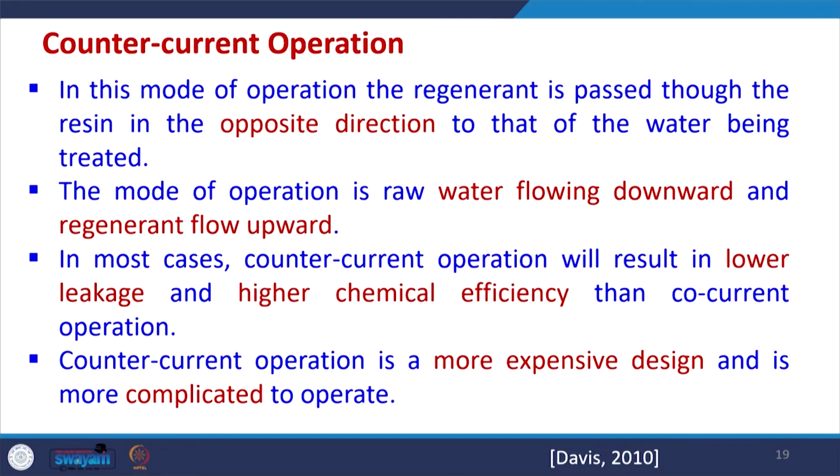Similarly, we may have a counter current mode of operation also. In this mode of operation the regenerant is passed through the resin in the opposite direction. So, that means during regeneration the regenerant will pass in the opposite direction to that of the water being treated.